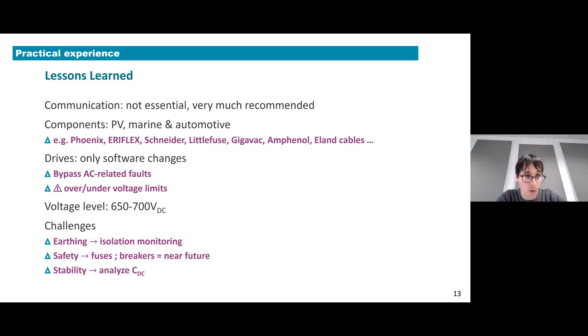Actually, all the drives which we purchased, which we used, were designed to be used in an AC case and they have an internal DC bus. We could feed them directly from the internal DC bus. That is because most drives these days have the option to have some kind of a minimalistic DC distribution when you stick to one brand.